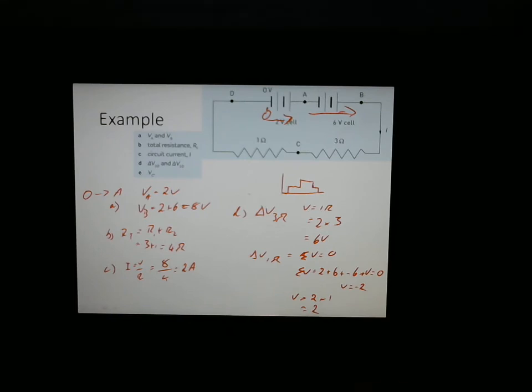But when I've used Ohm's law here, my resistance doesn't have a direction, my current doesn't have a direction being applied to this, I just work out that the voltage being used going through it must be equal to 2, and I have to interpret that: that's the change in voltage, must be negative 2 in this case. You have to use a bit of context knowledge in order to interpret whether these things need a negative or a positive sign on it.